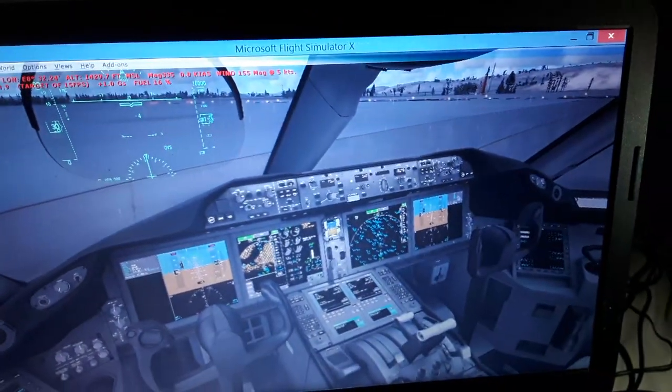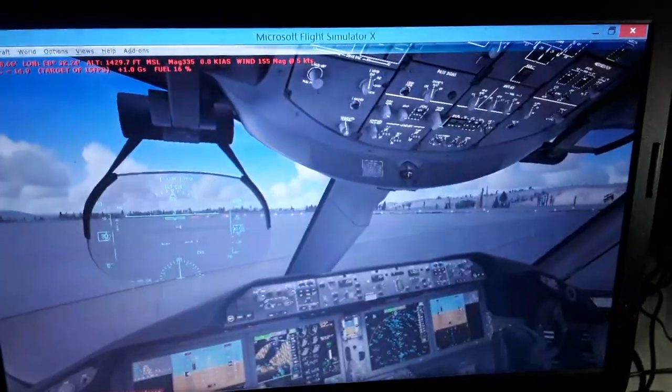Also we have the attitude indicator with the pitch ladder degrees and the bank angle in degrees, the artificial horizon with the attitude indicator, also the LSZH localizer. We have the LSZH localizer, the radio frequency transmitter from the runway threshold antennas that transmits radio frequency and is received by the onboard antennas of the aircraft to generate the horizontal localizer and the vertical glide slope angle for approach and landing.